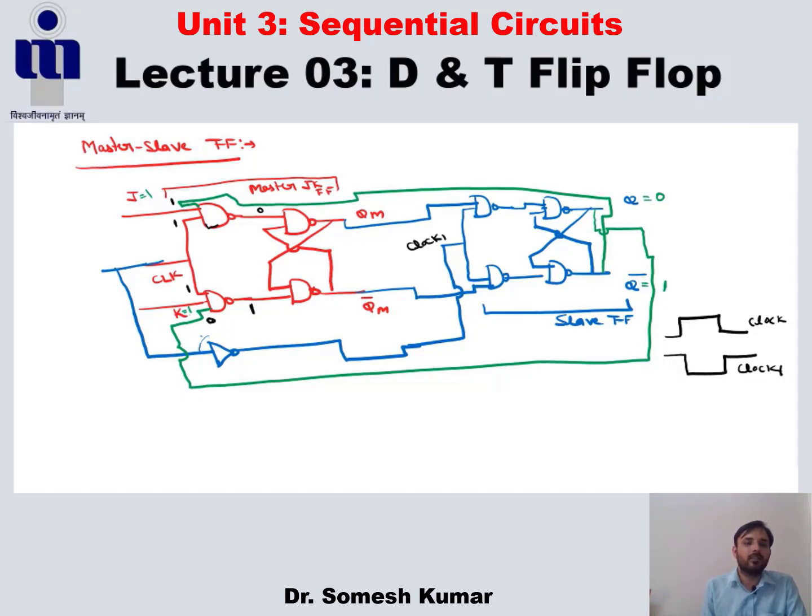And this is basically our latch. So if the inputs of the latch are 0, 1, then what will be the output? The output is basically 1 and 0. Please note that in the positive cycle only, the master flip-flop becomes on and the slave flip-flop becomes off in this state, because this is the negative level. So that is why this slave flip-flop is off in this state.